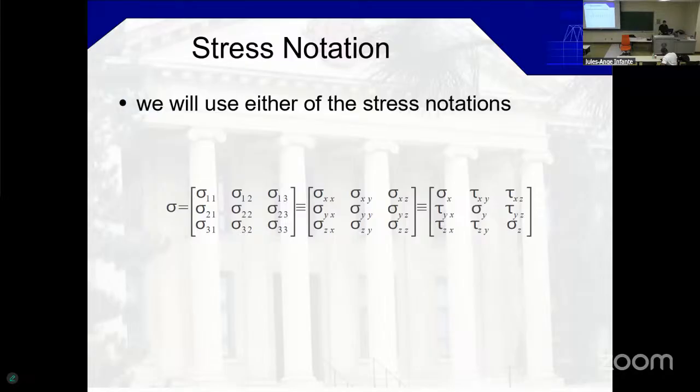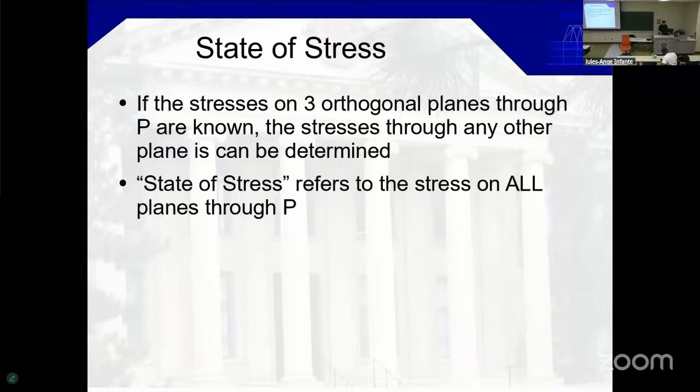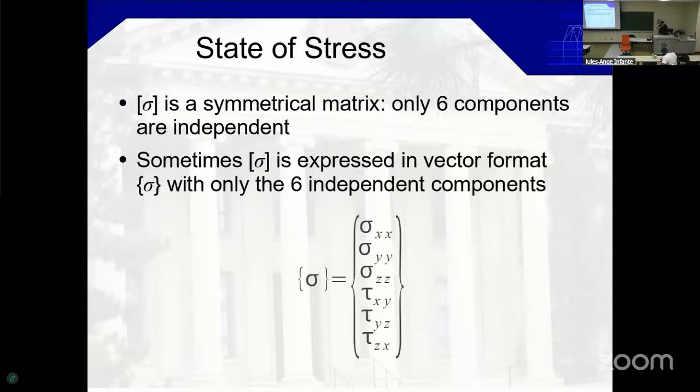No, and very often it is solved by representing the stress tensor as a vector. This is very commonly used whenever you're working with finite element programs. So at the stresses at each node, you solve for 6 values. And it's very useful because you've essentially removed 1/3 of all the values. And when you think of your matrices that are square, 1/3 means that you are 1/9.